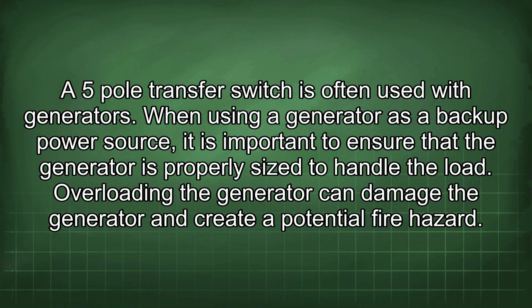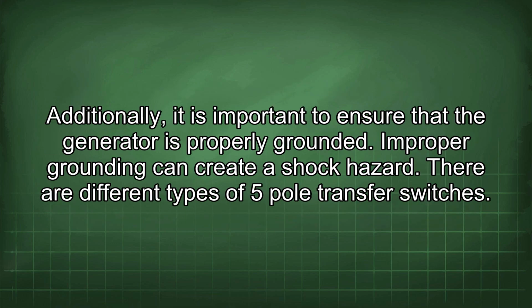A 5-pole transfer switch is often used with generators. When using a generator as a backup power source, it is important to ensure that the generator is properly sized to handle the load. Overloading the generator can damage the generator and create a potential fire hazard. Additionally, it is important to ensure that the generator is properly grounded. Improper grounding can create a shock hazard.